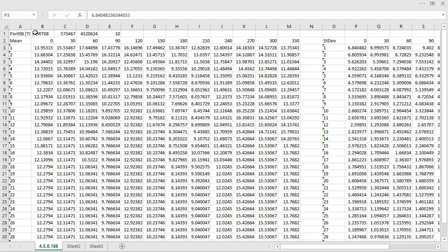So here at the top line you have some identifiers, and then you have the position and the height of the observation. Then you have a table here which is turbulence intensity, and then the mean of all observations, and then it's sorted into sectors here, the same sectors as your wind climates, and in wind speed bins like this. So here you have the mean of the observation, and here you have the standard deviations of all the turbulence intensity.